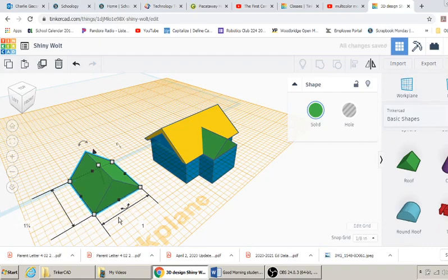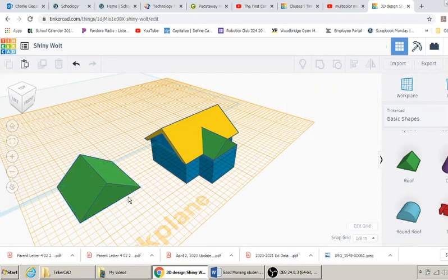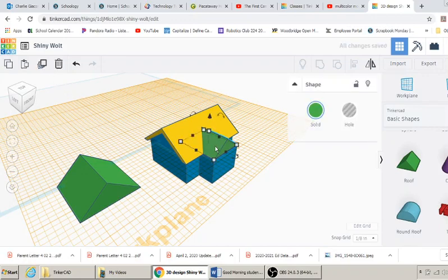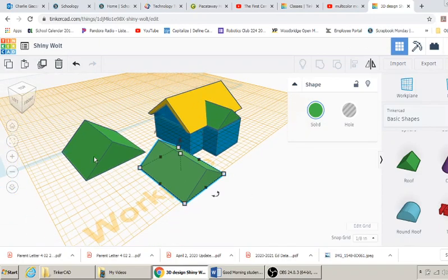Okay, I now need to make it wider by 1/8 of an inch from both directions, so that should be 1 1/4, 1.25. And then I have to add 1/8 inch to the height. It was 3/8 plus another 1/8, 4/8 is 1/2 inch, 0.5, so that's the default. Okay, there's our front roof. Now I'm going to take this, make a copy of it, drag the copy over, and do I have to make it a little longer? No, it's the same length.